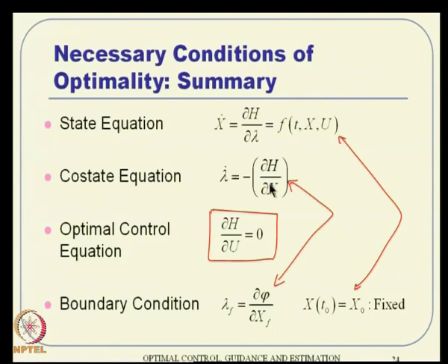One more comment on the way: if the state equation happens to be stable, most likely this co-state equation will happen to be unstable. So, the idea that I told just now, that initially you guess some lambda 0 and integrate it further, is not really very good, because for a stable system this equation is anyway unstable, and in numerical integration of an unstable differential equation, the error of the initial condition guess will be amplified quite heavily.